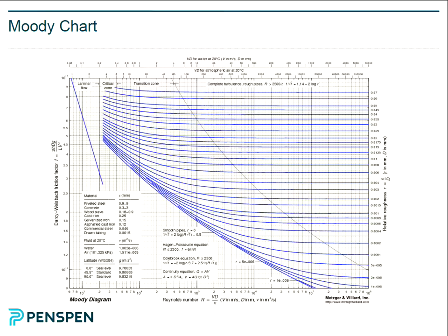So typically a roughness for carbon steel is 0.05 millimeters. Clean steel 0.02. Heavily corroded steel can be as high as 1. This is what's published, but I know from my own experience, if you measure the pressure drop for a very heavily corroded light water injection line, for example, and you work back to the friction factor, I've worked out under some situations you'll get a roughness of about 5 millimeters.